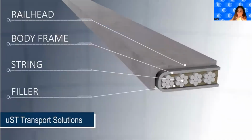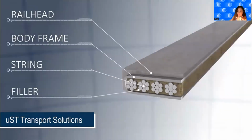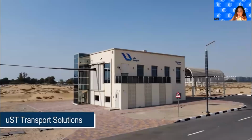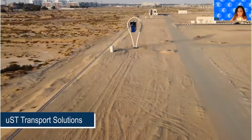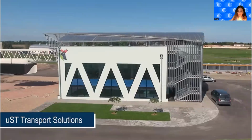It is a steel or composite beam containing a bundle of wires, strings, pre-stressed with stretching in its core and fitted with a rail head. The horizontal load from stretching is taken by anchor supports installed at a distance of up to 5 kilometers from each other. They can be combined with buildings for various purposes, including passenger stations and cargo terminals, as well as